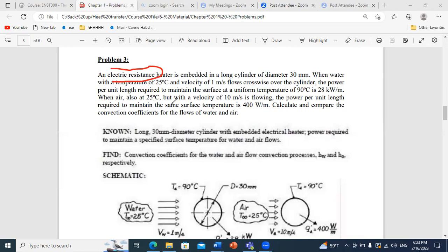In this problem, we can understand, for example, how we do the design of cooling systems. Whenever you have a cooling application, you should select a convenient fluid to perform the cooling operation. And of course, as we'll see here, the cooling effect of water is much larger than the cooling effect of air. And this is the case in general when you compare convection when using liquids. It's much more important than convection when using gases because the liquids are characterized by relatively high values of h.